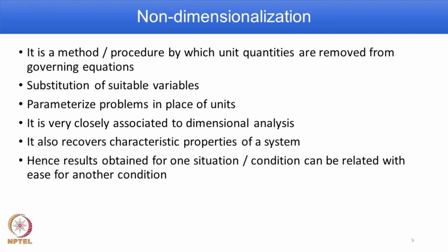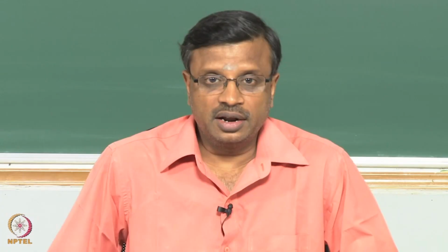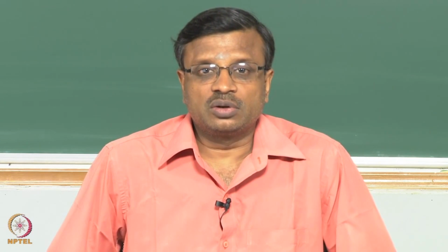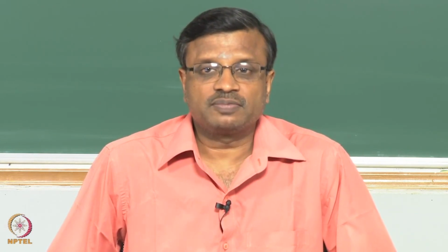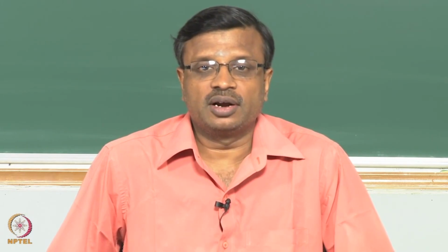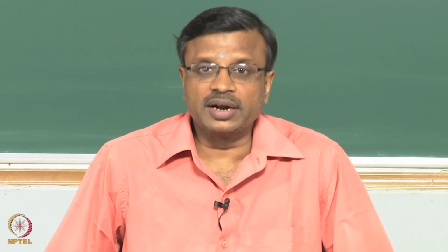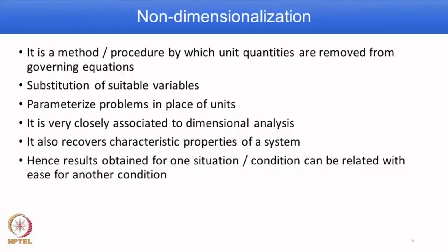Now, the advantage is, suppose you are doing an experiment or running a simulation for one particular geometrical condition or flow condition, and there is a need to repeat it for some other condition. If you do non-dimensionalization, then you do not have to repeat the cases for different situations. Results obtained for one situation or condition can be obtained with ease for another condition.